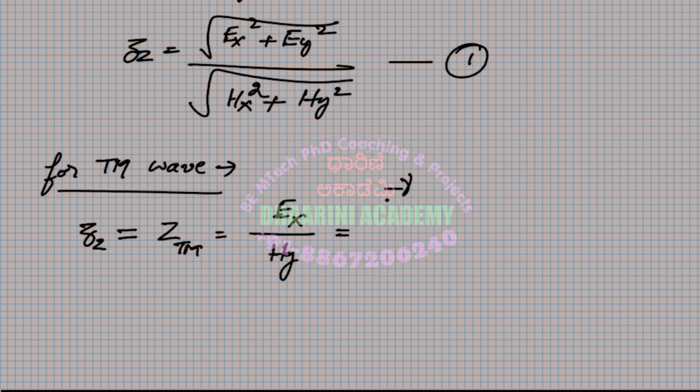So this is minus gamma divided by h square, partial derivative dou Ez divided by dou x, minus j omega mu divided by h square, partial derivative dou Hz divided by dou y. This is the numerator part. Let me substitute the required denominator as well.